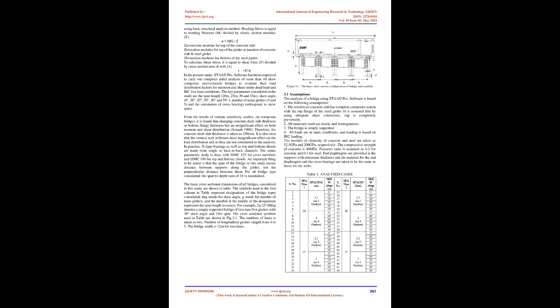Trilok Gupta and Anurag Mishra, 2007. A study on the behavior of T-beam skew bridges with respect to support reactions under standard IRC-70R wheeled loading is presented, and the study was based on the analytical modeling of T-beam bridges by the grillage analogy method. Effects of support reactions for different spans have been studied.